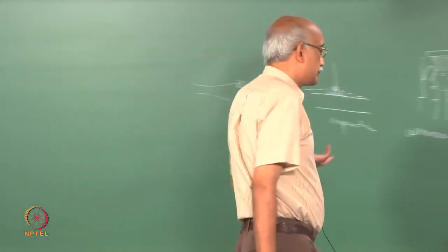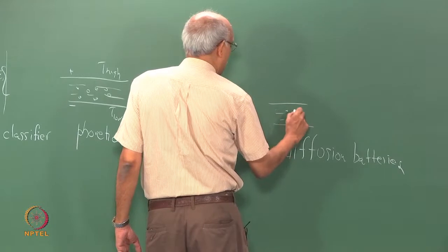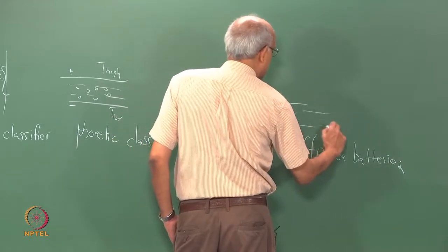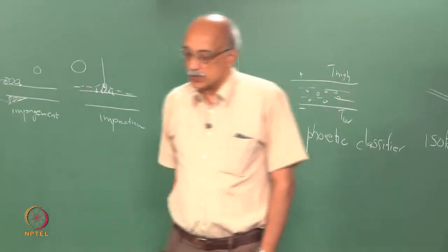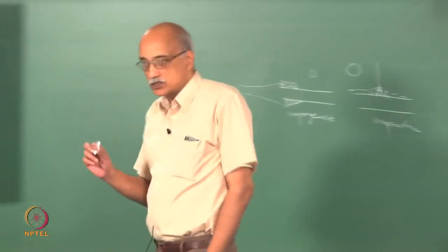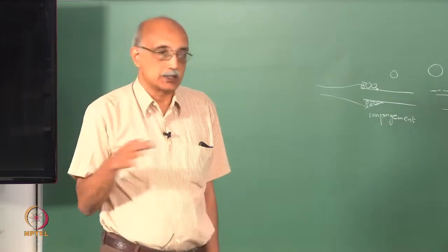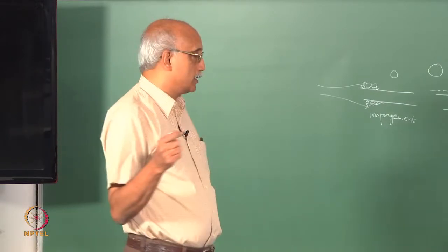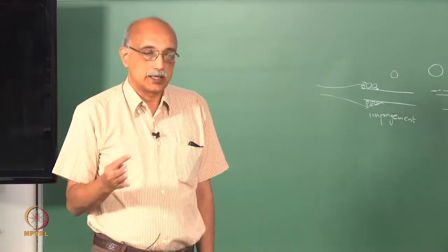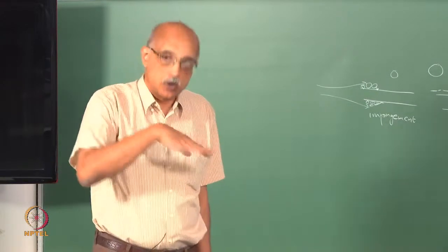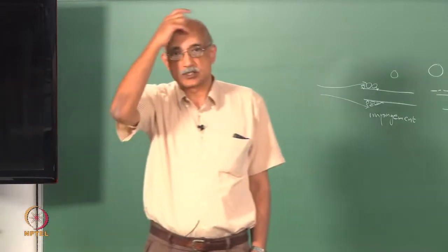You have an entrained airstream in which you have particles, and you set up these screens at different locations along the flow path. So, here what will happen is the finest particles actually move the fastest. Turns out that diffusivity scales as 1 over particle size squared. So, the finest particles will be collected in the first screen itself, whereas larger particles will take longer to diffuse from the bulk of the flow and find the collection surface.